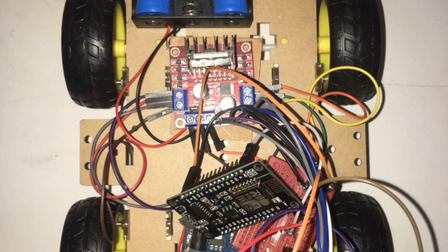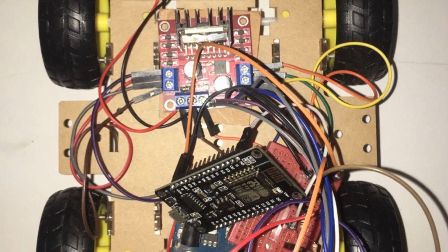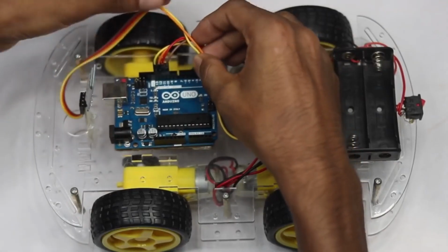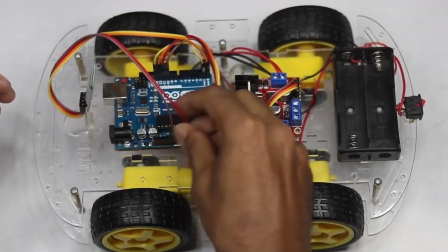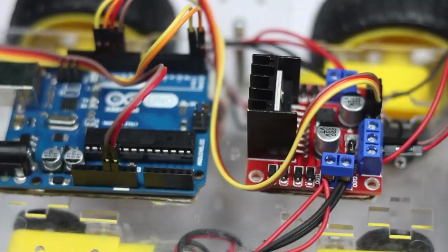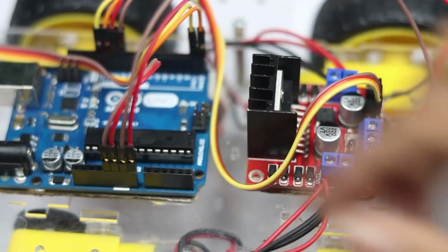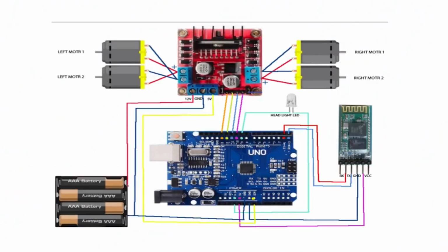A voltage divider circuit is connected to a Wi-Fi module on the ADC pin. The circuit is designed to measure the car's battery, then send the data to the Wi-Fi module. The Wi-Fi module is then coded by Arduino IDE to send the battery percentage to the cloud and keep updating the data each 10 seconds.